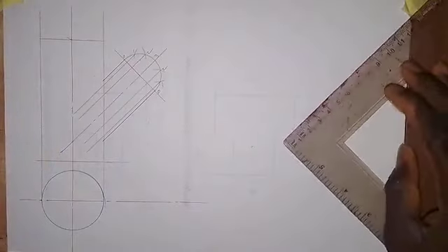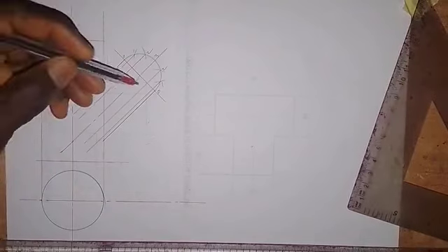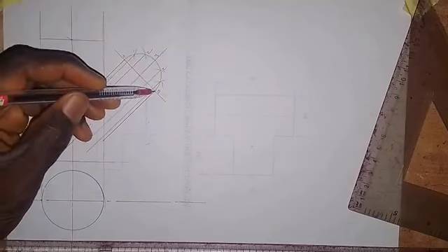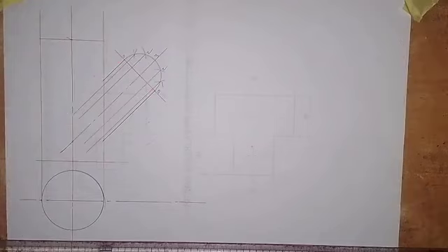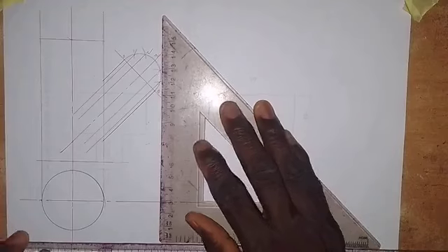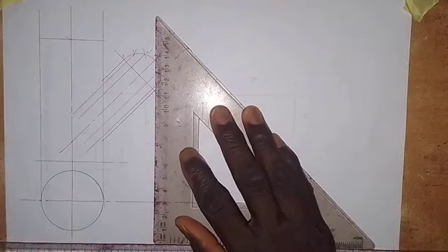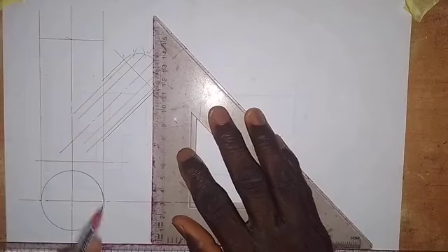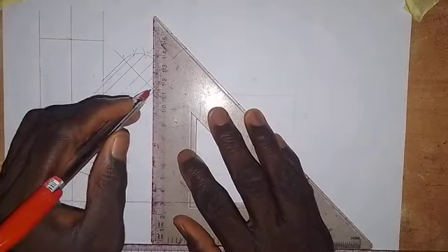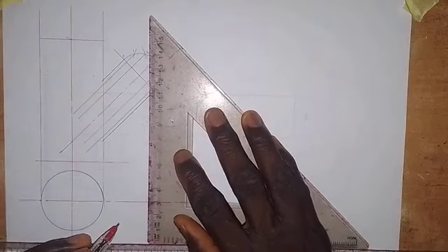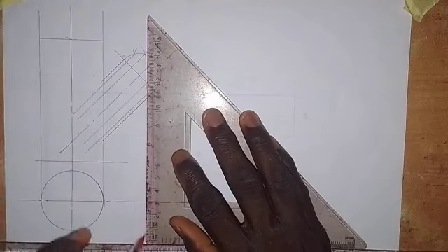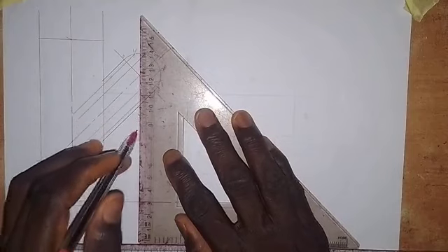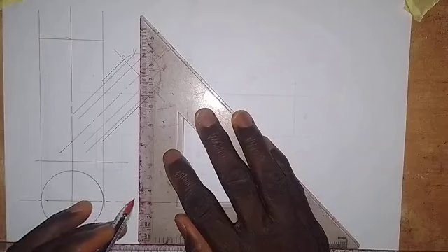Then the next thing that we are going to do is draw a line from each point that we have here, not on the semicircle, but on this line. So what I mean is this. With my set square set at point 0, I'm going to draw a vertical line from that point 0 down here. Then from point 1, I will also draw a vertical line down, and from point 2 here, I will draw a vertical line down. From point 3, we are going to draw a vertical center line down here. Okay, so draw it down.